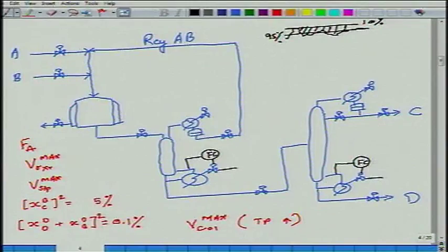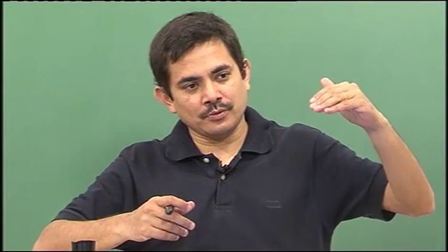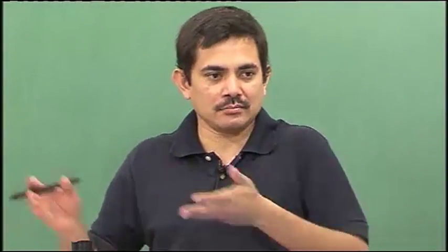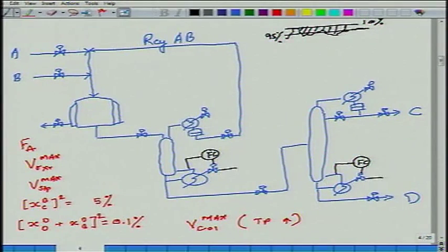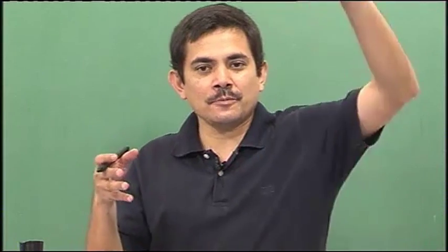Now, you notice that the manipulation handle to maintain boil up is right there. So, this controller will be really tight. If this controller is really tight, then my boil up will be almost constant all the time, because the flow controller does not let it vary at all. See, temperature controller was deliberately varying it to hold temperature constant.